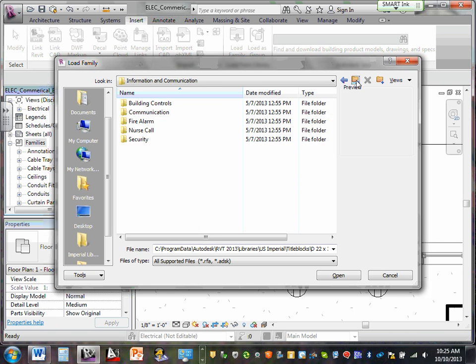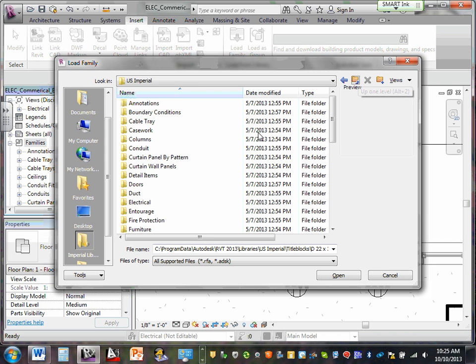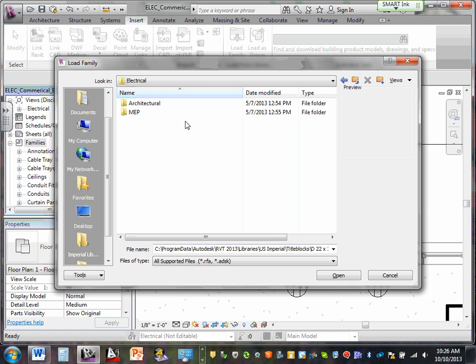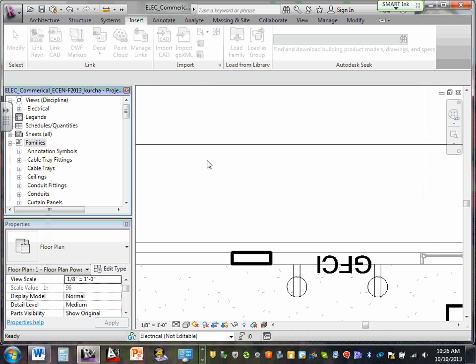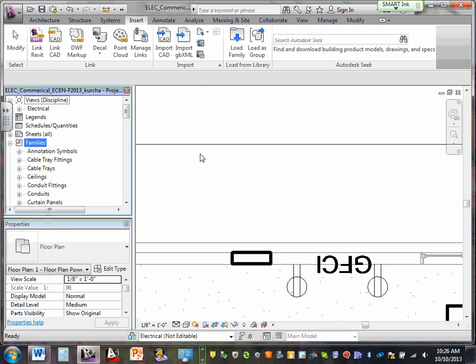Okay, so I'm going to do one thing, and I want you guys just to load one thing, will you? Everybody's there. Go back all the way to electrical, and give me a thumbs up when you're there. Brian, everybody's there at electrical? Karen, okay. Double click on electrical. Go to MEP, mechanical, electrical, and plumbing. Go to electrical power. Go to distribution, and go get me an auto transfer switch. Can you guys see the auto transfer switch here? Everybody can see that? Click on it, or double click on it, or just click and open. You have just loaded an auto transfer switch.